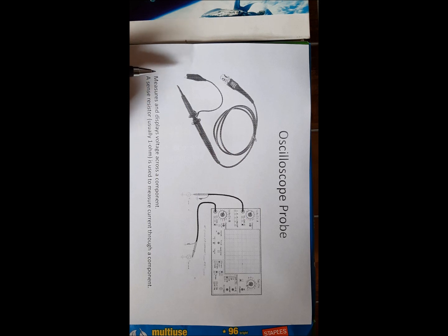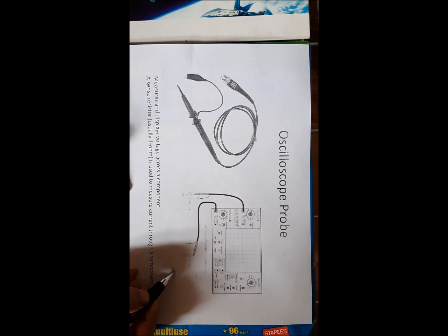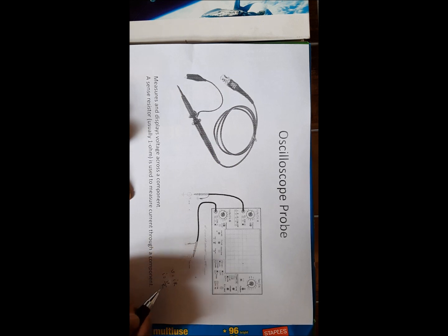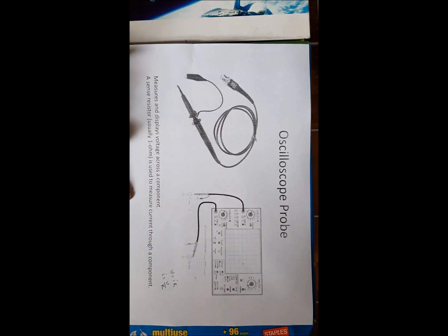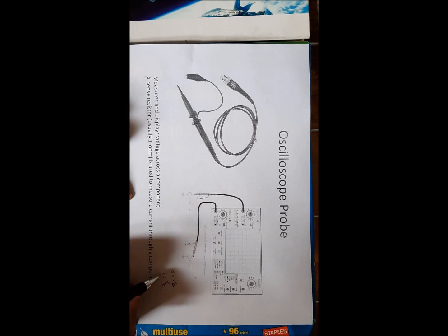If you want to measure current, we basically measure voltage across a resistance. As you know, according to Ohm's law, V equals IR. So once you find the voltage, you will get the current. Current will be voltage over R. For a resistance, voltage and current are in phase, with only a linear multiplication factor of R. So if you divide voltage by R, you can get the current. That's why the voltage wave shape across a resistor is the same as the current wave shape of that circuit.